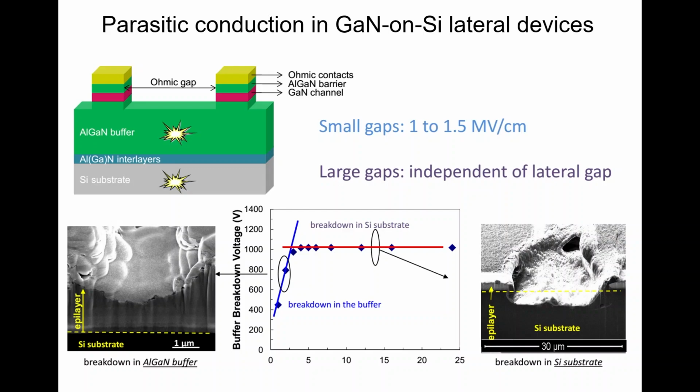That happened, you see, you have the silicon substrate here, and you are really breaking down in the bulk, in the buffer layer, sorry. So the catastrophic breakdown is here. These are real cross-sections. And another one with large gate drain distance, where you really break down through the substrate. So your substrate ends up here. So you have a physical proof of the breakdown mechanism, let's say.